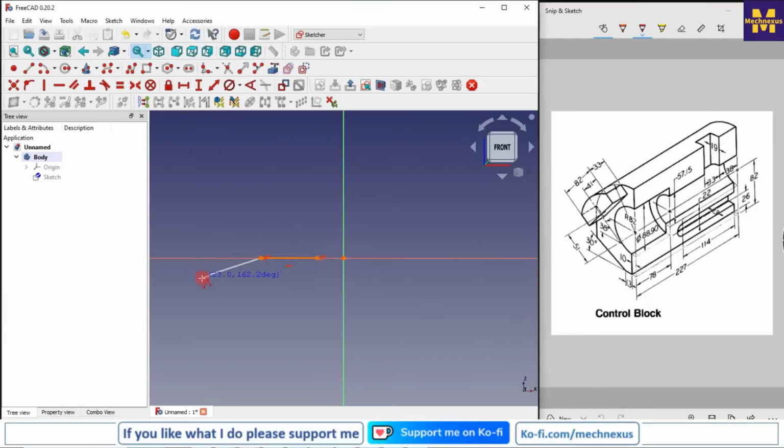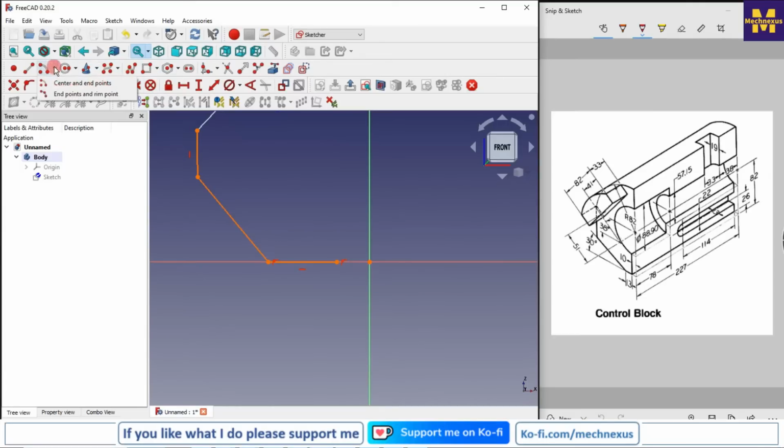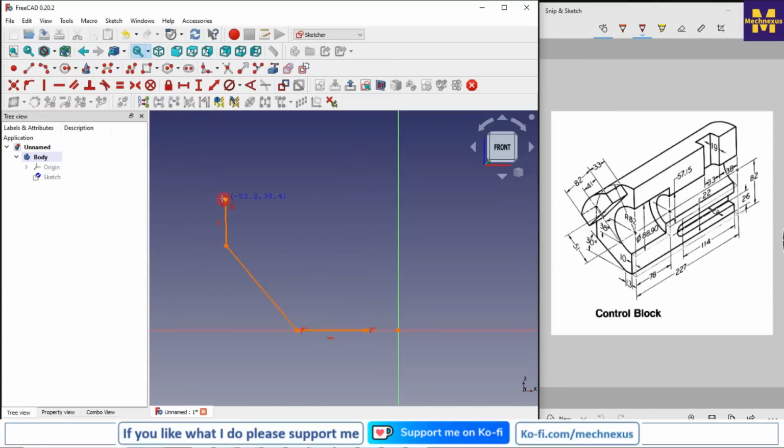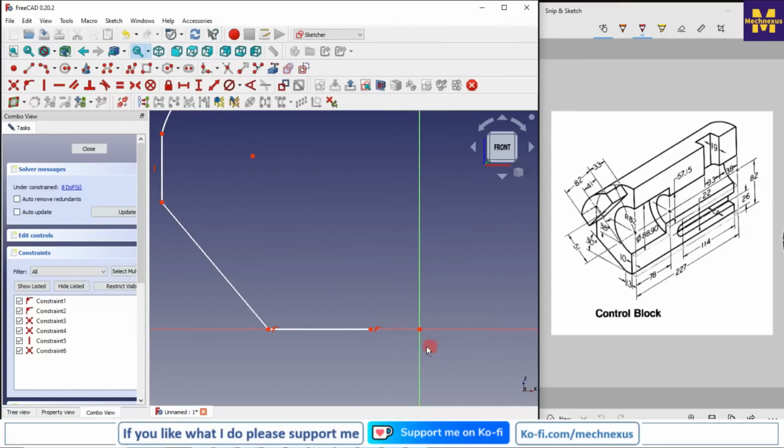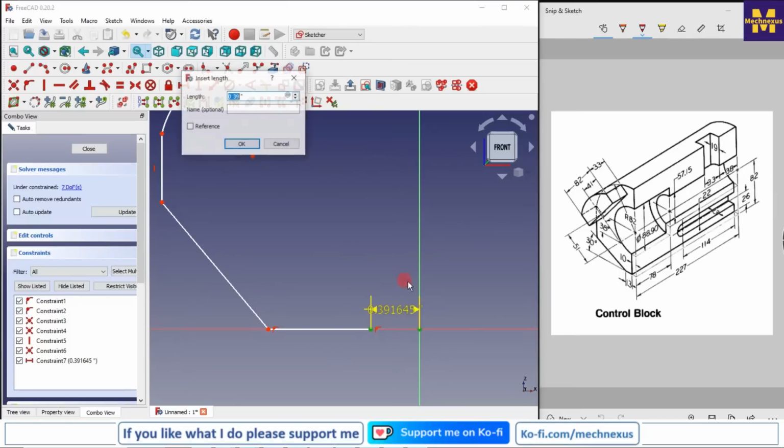and I will draw a line, and then I will draw this line, and it should be straight, and then here would be the 3-point arc. So I will create a 3-point arc. Okay, and now we will move to the combo view and we will see the conflict in constraint. So I will delete it, and now I will give the dimension.